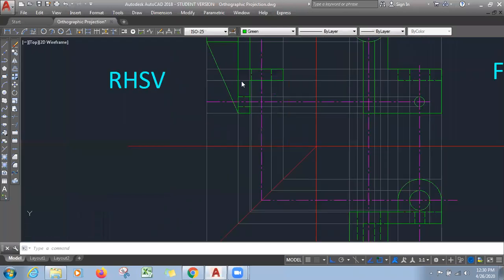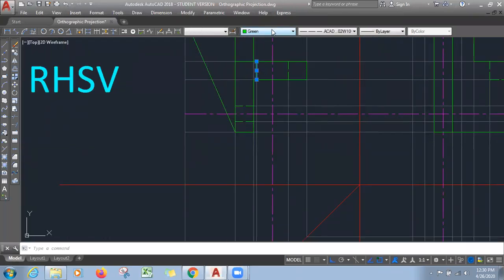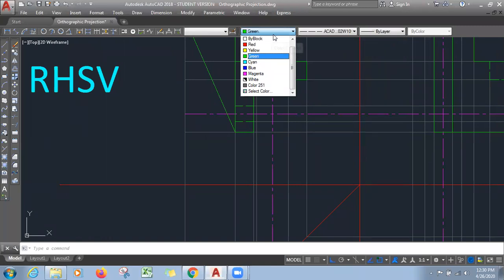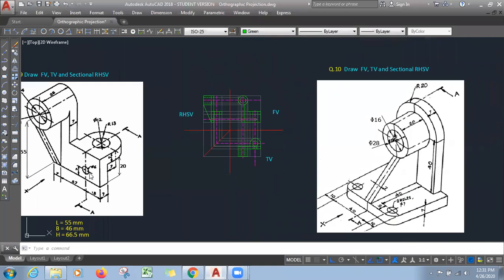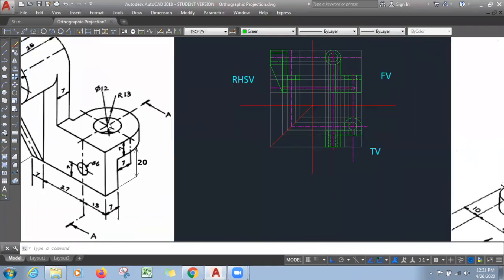Okay, so what does hole exposed mean? Here there will be thick lines. You see here there will be a thick line. Similarly at this place there will be a thick line. Again at this place there will be a thick line, at this place there will be a thick line. Okay, and cutting doesn't take place at these holes, the hole portion. So for the remaining portion we can show hatching. Okay, then go for hatch.